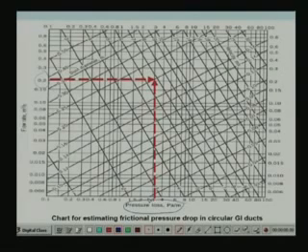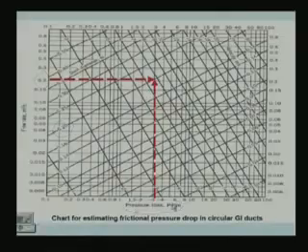And I am using a rectangular duct. So, the rectangular duct should have an equivalent diameter of 0.2, because this is where the two lines intercept. I can get this from the standard chart, but the actual velocity will not be between 6 to 7 meter per second. So, you cannot use the velocity values that you obtain from the chart, you can use only the equivalent diameter values from the chart.